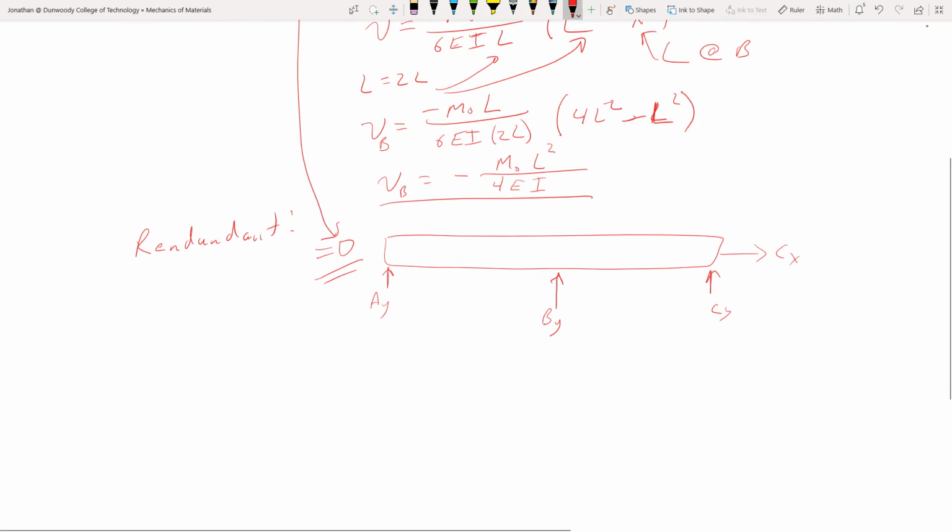So we're going to look for what this is, and maybe I should put a subscript 1 on this one here. It's our first deflection, now our second deflection. So in this case, we're pushing right in the middle of the beam. Our deflection here is that first case from Appendix C, simply supported. In this case, our max deflection is right at that point, so V max is negative PL cubed over 48EI.